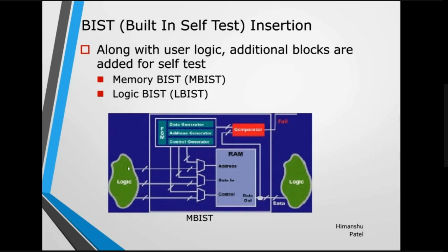The transition time inside the combinational logic gate is less, but each sequential cell will take 1 nanosecond of time. On top of it you have setup time and hold time to make the value stable, so there will not be any rush between the data transition or data loss. That we'll learn in the concepts.